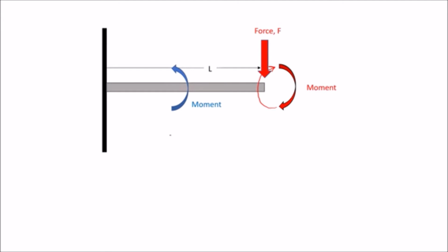And we can do that by applying a force here. A force of G applied upwards would create a counterclockwise moment. And this counterclockwise moment, if our force G was large enough and our distance x was small enough, we could create the same moment here, and thus the sum of our moments acting on the beam by the forces would equal 0.